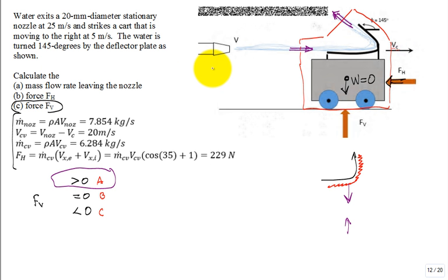That's correct. That's a good way of looking at it. If you take that cart and all of a sudden you don't support it anymore from any external force, and it's turning that fluid and pushing it up, well, that is going to push the cart and everything else that the fluid's hitting against, pushing it down. Just like if you didn't supply this anymore, which way would the cart go if the water jet was turned on? The cart would accelerate in that direction. True? And here it would accelerate in the downward direction if you took away those supporting forces.